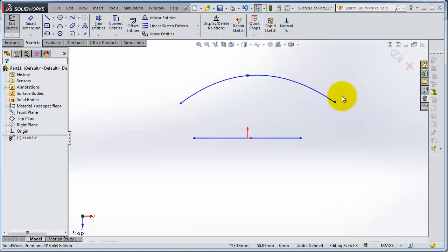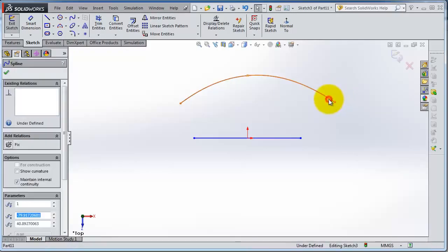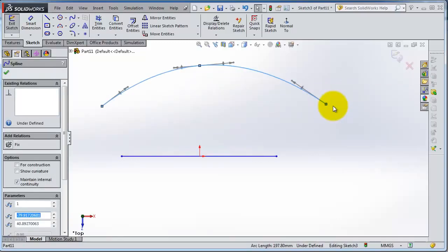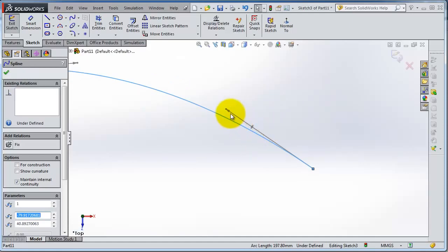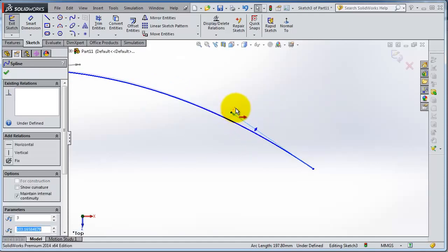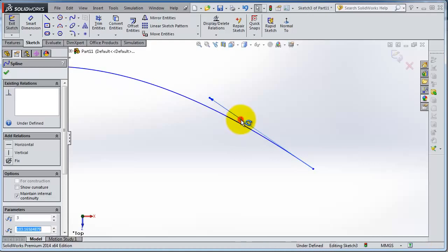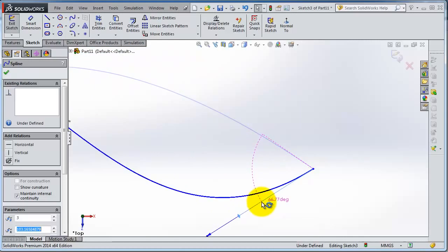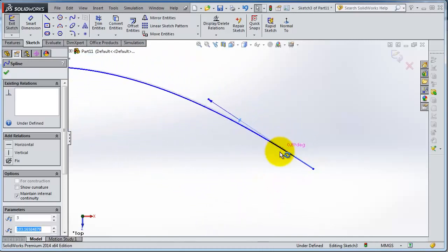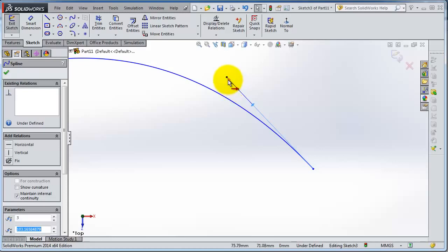right click, select. If you click on the spline, you'll notice each point has 2 important things. You have the handle and you have the direction. So if you select this, you are able to change the size of the handle, and the other one changes the direction of that spline edge. So you have 2 things here to think about: the size and the direction.